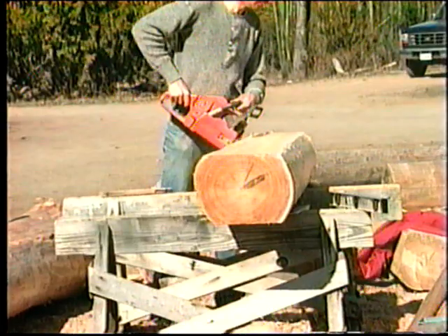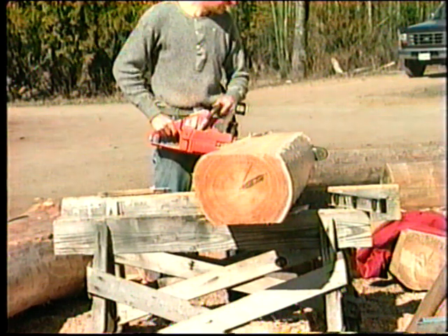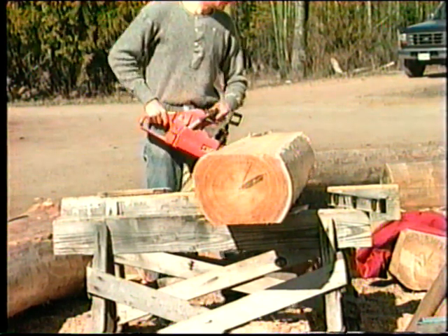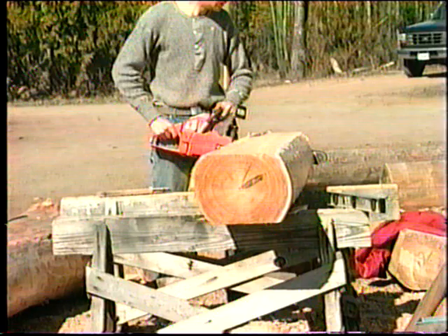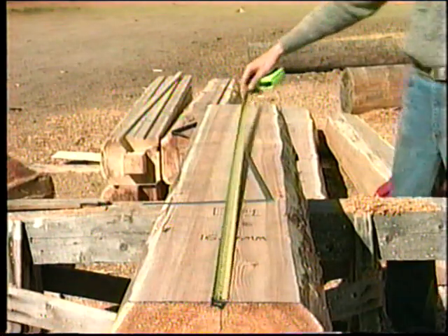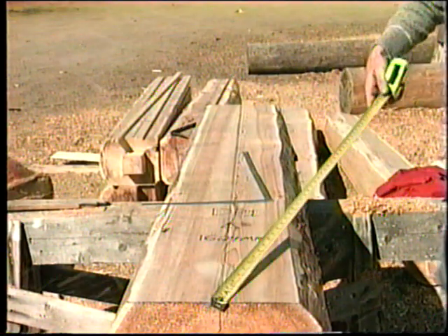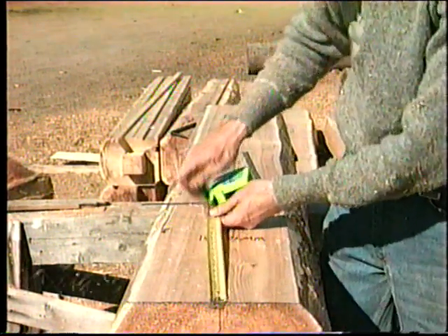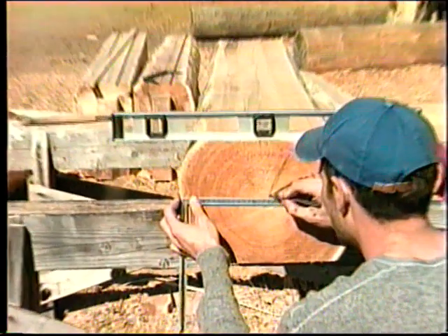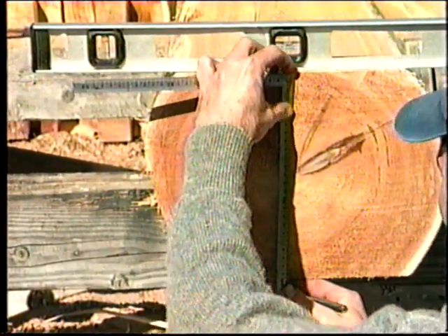Prepare the post logs by flattening them on each side to a width that will be equal to the framing material plus the sheathing to be used, let's say 150 millimeters or 6 inches. The width of the post itself can be a random measurement. Make sure that the post is long enough. From center lines, place a cut line around the top of the post about 100 millimeters from the end. Use the two squares to obtain an accurate layout.